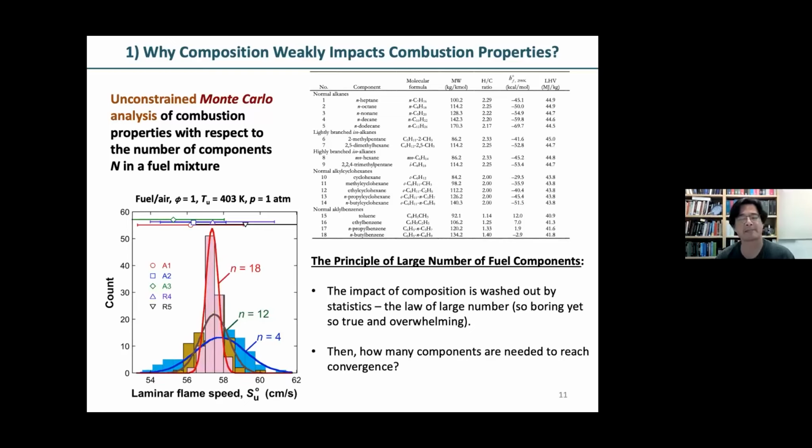To summarize, we'll have pyrolysis first, oxidation second. Oxidation takes much longer, and it is, of course, rate limiting. That's a key characteristic of burning large hydrocarbon real fuel components. Okay, the oxidation process takes 700 microseconds, and oxidation of ethylene is rate limiting.